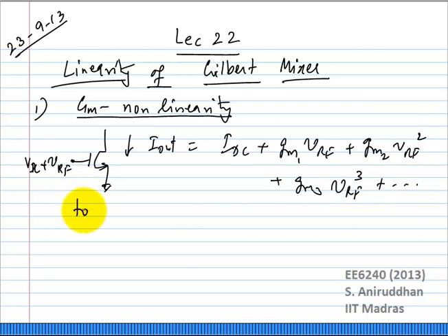If you want to improve IIP3, apart from the circuit techniques we talked about, what else can you do? What do you need to do to improve IIP3? So yeah, you can use the resistive degeneration, inductive degeneration and so on. But fundamentally for the transistor, what can you do? The nonlinearity depends on the bias point of the transistor, right? Primarily on the VGS minus VT.